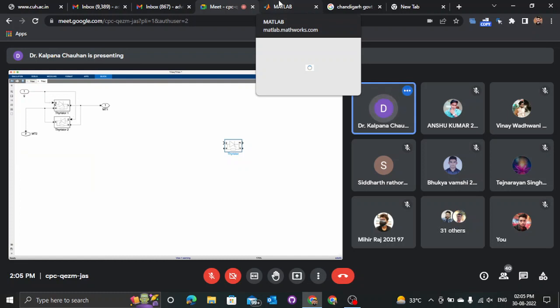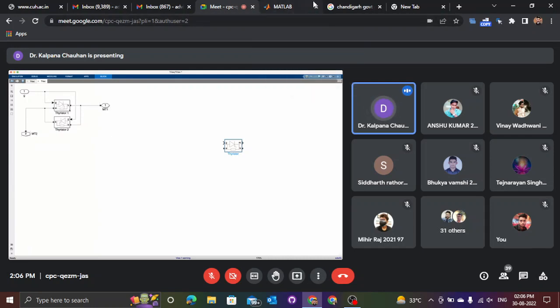Just connect this gate of the other thyristor, the anode to the cathode of the first and second thyristor, and this anode is connected to this input, this empty one. This empty one is the output port of thyristor T1, and this is the go-to block. Okay, we can just make the go-to like this. Just click on this.